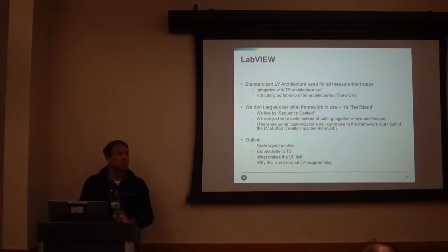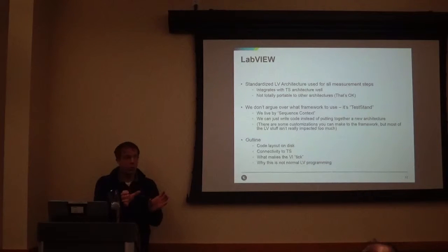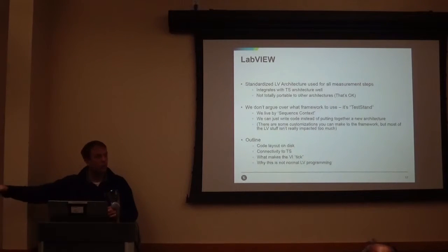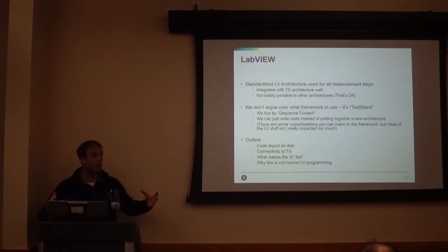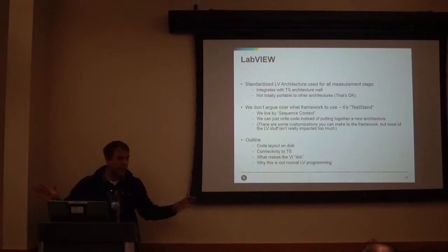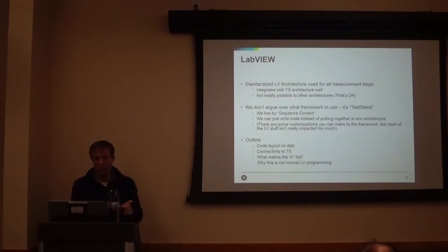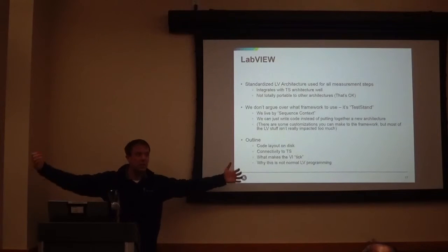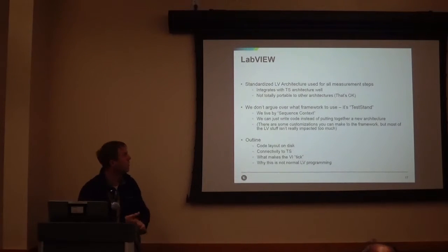It also means that our LabVIEW code is lots and lots of small little modules: go measure the voltage of this, go measure the noise of this, go measure the bandwidth of this. Everything comes back to TestStand as our overall architecture, our executive and our UI, which means a lot of the big picture LabVIEW OO stuff we've been seeing earlier today doesn't matter to us. We write small little LabVIEW modules that plug into TestStand, which is our big behemoth.